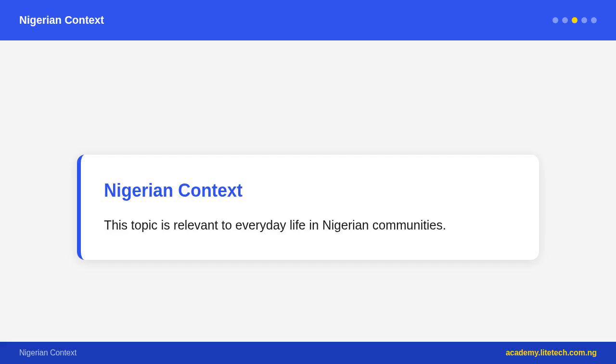bevel gears, which have teeth on a conical surface and are used to transmit motion between shafts that are at an angle to each other. The rear axle of a car uses bevel gears to transfer power from the propeller shaft to the wheel axles at 90 degrees. And rack and pinion, which converts rotary motion to linear motion. The steering system of a car uses rack and pinion to convert the steering wheel's rotation into the sideways movement of the front wheels. Now let us study pulleys.